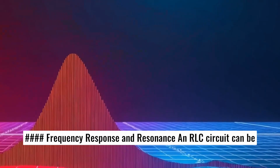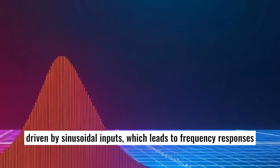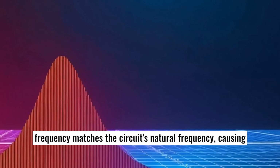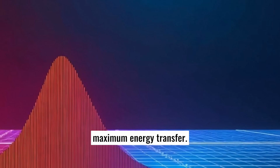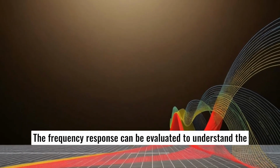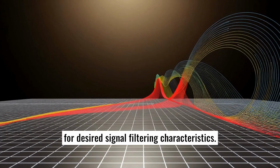Frequency response and resonance. An RLC circuit can be driven by sinusoidal inputs, which leads to frequency responses influenced by resonance. Resonance occurs when the input frequency matches the circuit's natural frequency, causing maximum energy transfer. The frequency response can be evaluated to understand the behavior of the circuit at different frequencies and configure it for desired signal filtering characteristics.